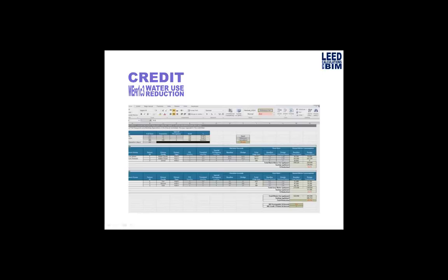In Revit, what will happen is they'll get orphaned. They're still there. They just don't have their host any longer. Even wall-based? Even wall-based. Often what happens is the design team will delete a wall and rebuild it. Right, there's a new wall there. But all the fixtures that were hosted on the wall are orphaned. They're still in the model, but they need to be reassociated. So look up "orphaned," I think is the term, and there's another term in the Revit help, and it will explain how to reassociate them.